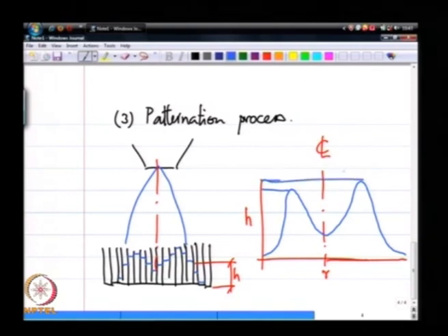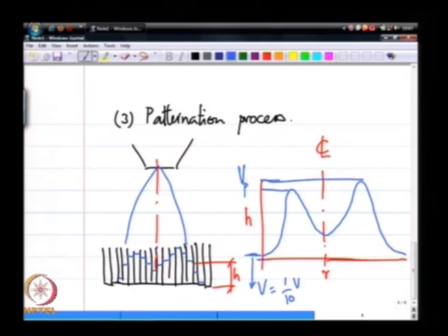And notice how I have intentionally drawn the peaks to have different values on either side of the center line. So, in a real spray there is no reason to expect symmetry in the spray. There is geometric symmetry in the nozzle, but very often your spray itself could be slightly off and there is no theoretical reason that they should always be exactly the same when applied to a practical spray nozzle.